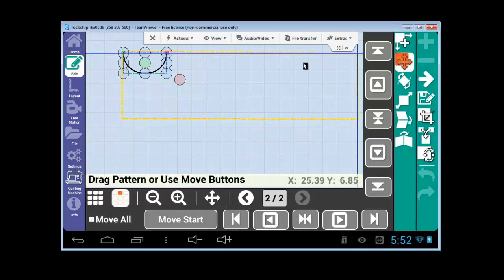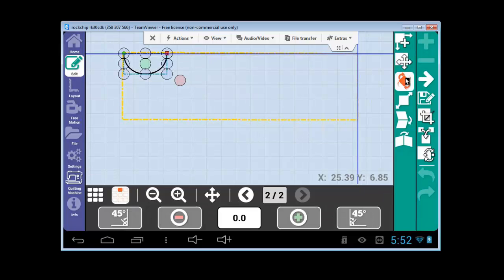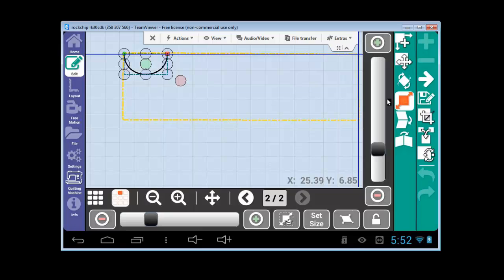I'm pretty sure we covered everything in the move menu. And we've covered rotate, which I saw you using pretty well, so that obviously made good sense. The main difference on this screen is knowing how to lock and unlock proportions, and knowing the difference between smart scale and morph. Morph is what you want if you want to stretch it out a little bit. This morph icon, do you see how it's highlighted white right now? That button will stretch the pattern out and make sure it fills all the space available.